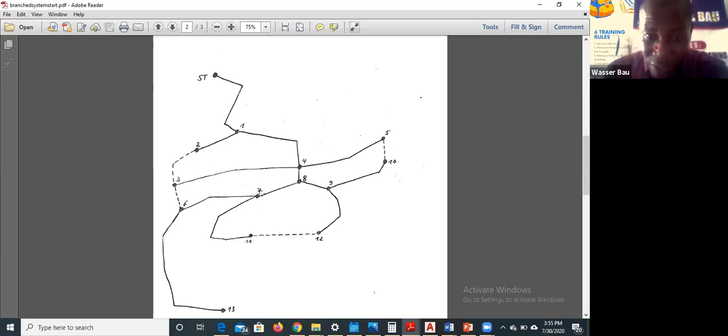And how did we get node 7? Node 7 is the addition of node 11 plus node 6 plus its own base demand. So here we got 0.18, here we got 1.15, then here we got 0.23, here we got 0.18. By the time we added them together, we got about 1.22.